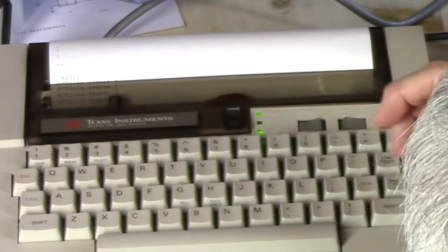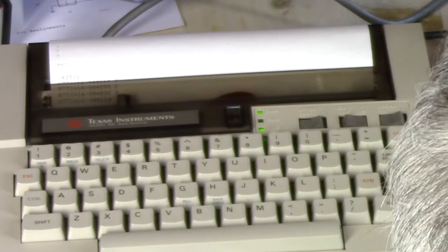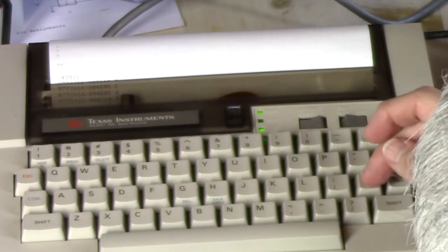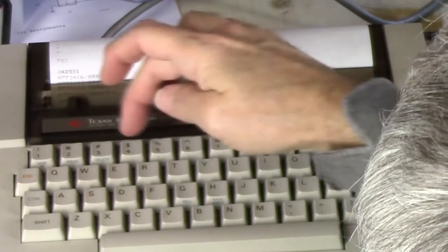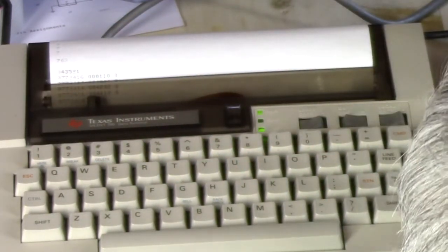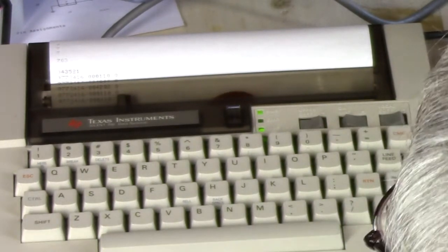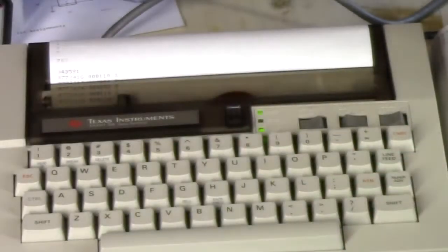772416, yeah, okay, I'm going to put 0 in there again. It's still 0, but we'll go through this as if we didn't know that. 772416. Now reading that data register will give me the value in location 0. And it is 110 octal, which is an H. How about that? Okay.